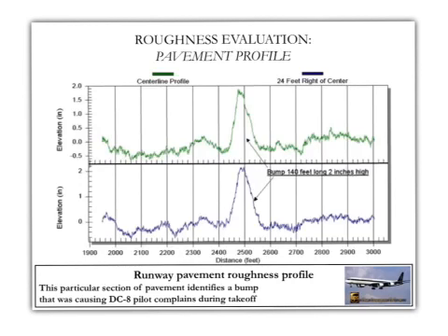Even if it's just 2 inches, at a very high speed it will generate a very significant bump that pilots kept complaining about. And yes, when we sent technicians to the runway in the field, they were able to capture that by simply having the pavement profile, which is elevation versus distance.